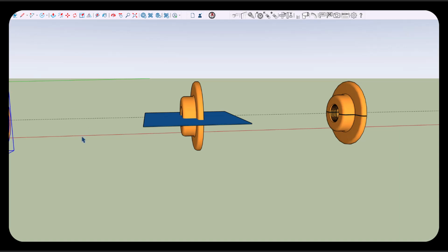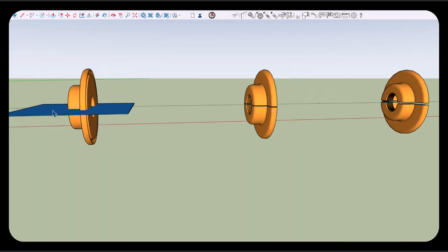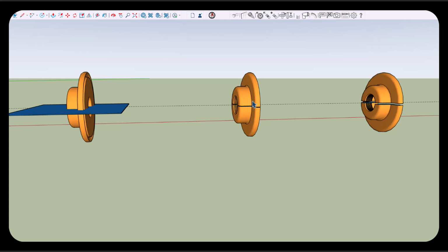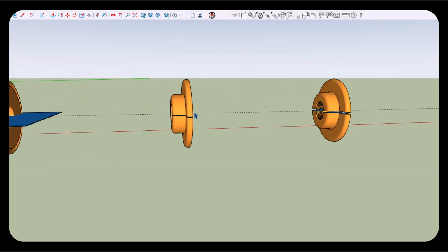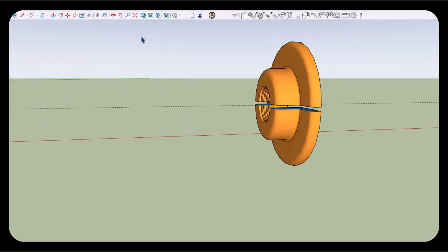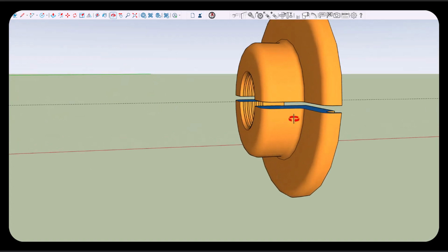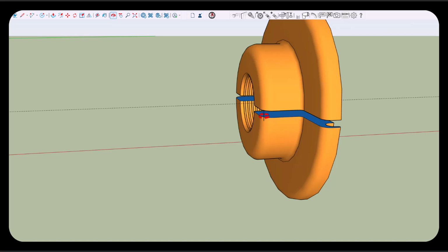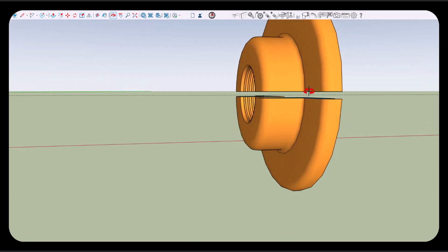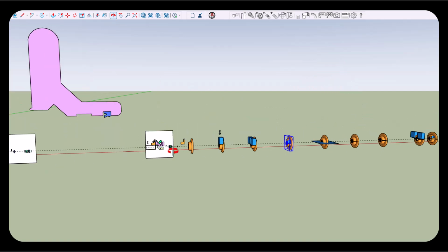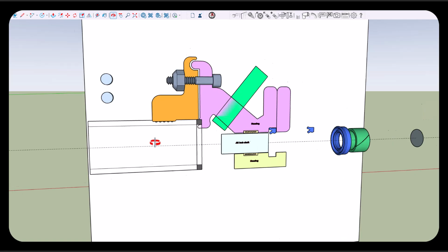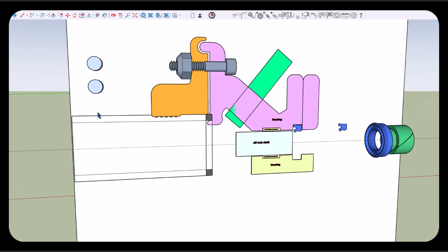So now you have these two pieces, and it's a little bit difficult to split them apart, but you get them apart, and then you take this piece here and you put it in your CNC machine, and you grind it down so this is flat and smooth, and the separation between them is 1/8 of an inch. And the way this is designed is, in the Delrin, there is a groove in it.